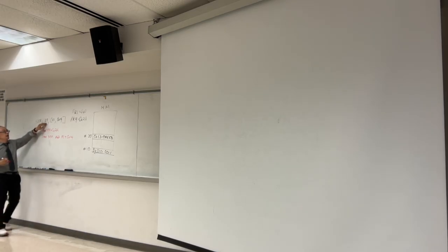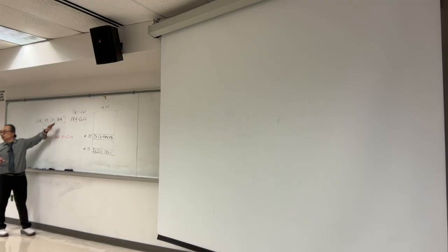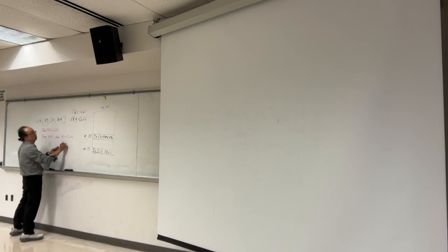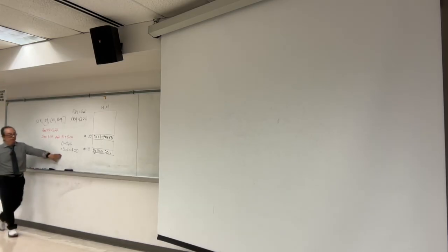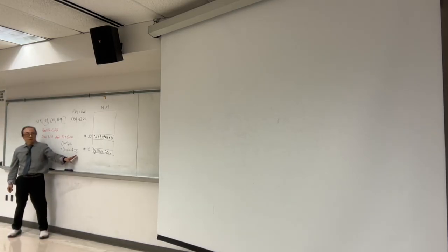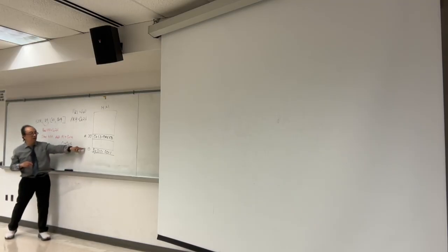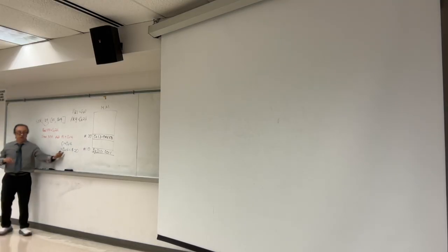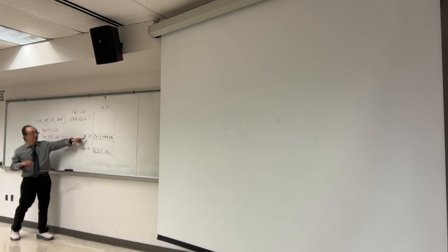We're going to read R9 and store that into main memory at the memory address R1 plus 0x14. R1 is 0 plus 0x14, and that is 0x14, and that is 20. So now we know the address. I may give you the address as hex or as decimal. You should really be careful whether this is a hex or decimal number. How do you know the number is hex? You're going to see 0x. If you don't see 0x, that's a decimal. We're good so far? And where's the 20? It's a 20 right there.